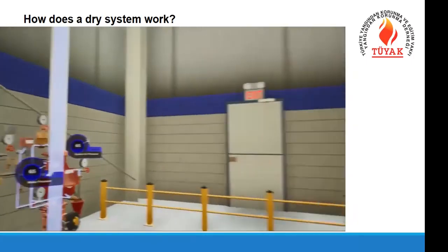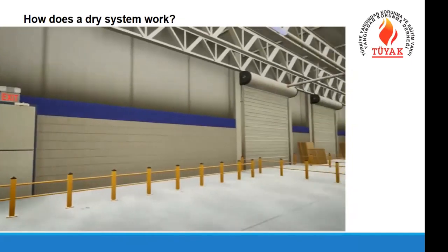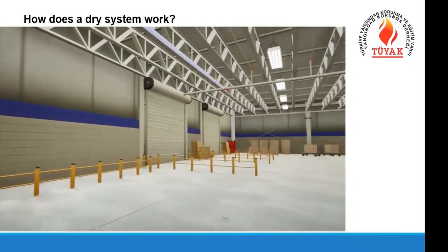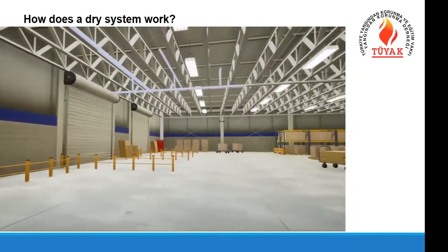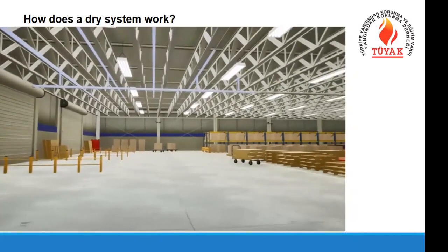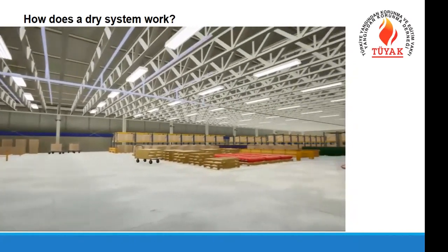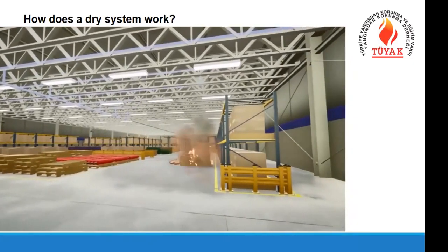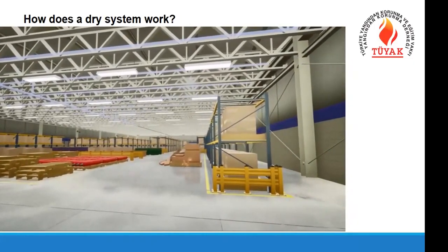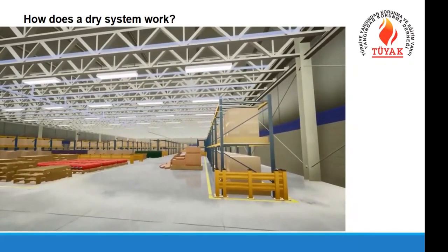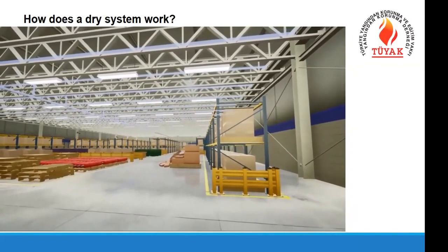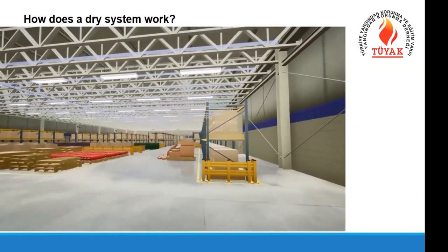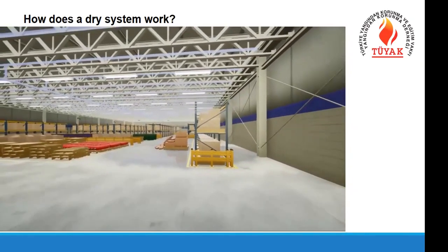Water flows through the system, taking the path of least resistance to the open sprinklers. Air pressure will remain trapped in the pipes that are not in the critical path to the open sprinklers. As time passes, water will displace the remaining air and the lines will fill with water. The sprinklers continue to control the fire until the fire department arrives.